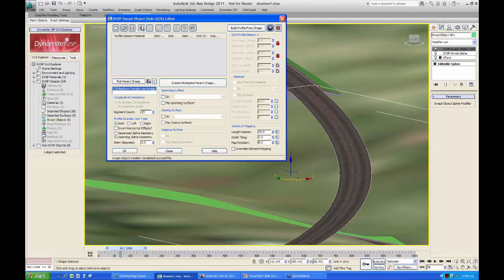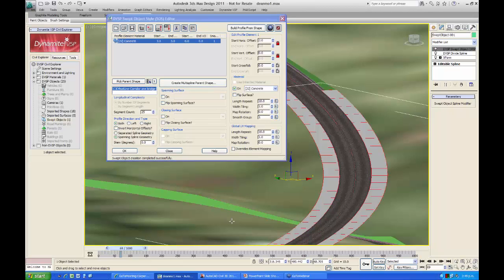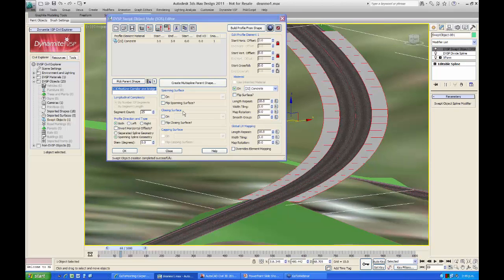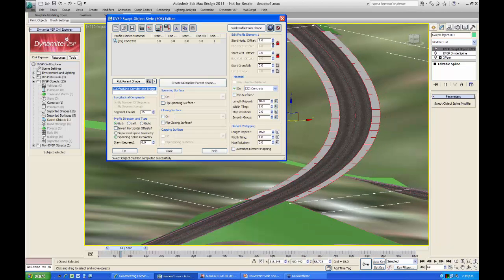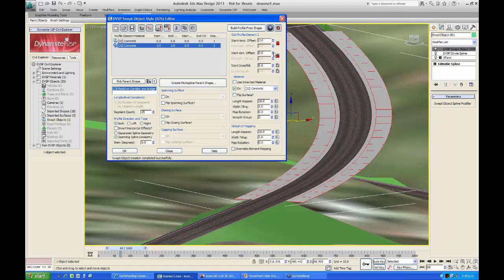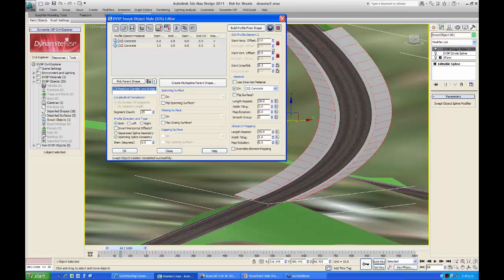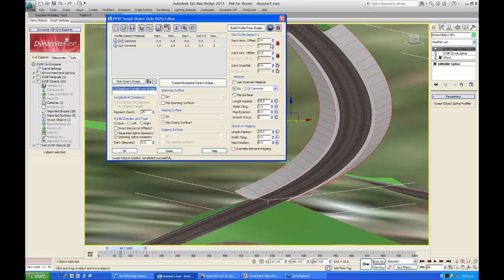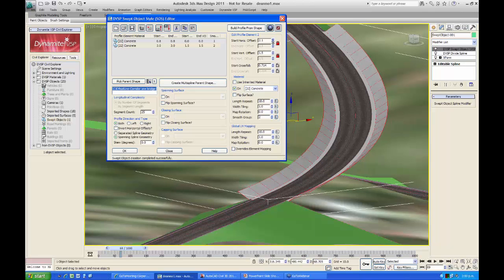So we make an entrance in this table, and you can see straight away it's starting to build these bridge elements out the side. It's concrete, and we've got some horizontal offsets, etc. So if I click and hold on these arrows, I can move them in and out as I need to. So let's make a horizontal, say it goes 0.8 of a meter horizontally, and then we go and make the next element. So hit the little next element here. Make our vertical offset of, say, plus 1.5 meters high, and we'll start the horizontal offset in a bit tighter.